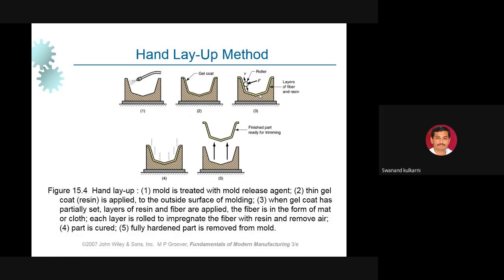Then this part is allowed to go through the curing process, as shown in this figure 4. Curing means it is kept as it is for 4 hours, 8 hours, 16 hours, or 24 hours, as per the curing period, which depends on the kind of matrix material we are using. With the help of that, we keep that time. And once this curing period is over, we remove this finished part.